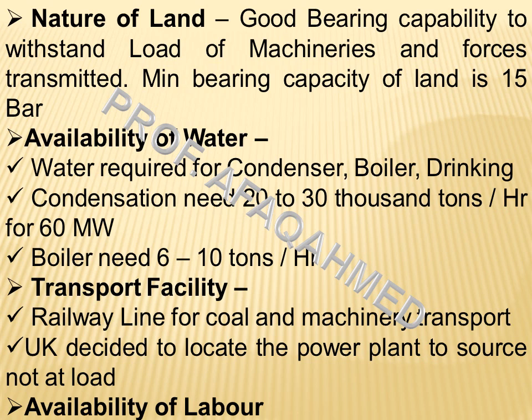Thus a million kilowatt capacity coal fired station at a distance of 700 miles from the nearest coal field would involve transport of 3.6 million tons of coal over the distance, and this will lock up some 10,000 wagons and 165 locomotives, representing a capital investment of about 175 million.